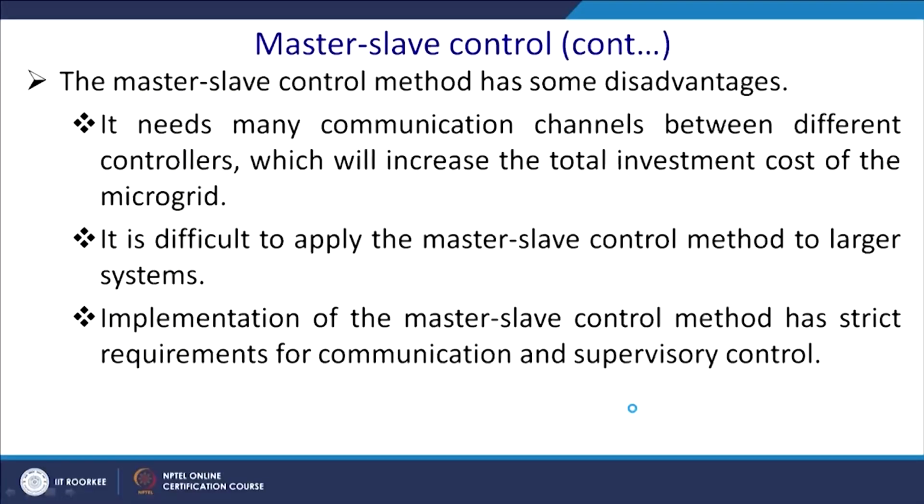Now let us come to the advantages and disadvantages of the master slave. The master slave control method has some disadvantages. One aspect is that it should communicate with individual DGs and ESS, and thus you require a faster communication channel.